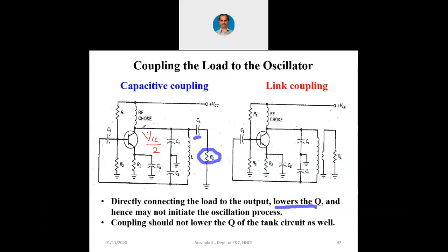Or if the resonant frequency is larger, then also the Q factor is larger, but the resonant frequency is the required frequency for the given application. So the only way to increase the Q factor is to have a reduced bandwidth. In order to have a reduced bandwidth, it is always advisable to have a high level tuning circuit. The tuning circuit's efficiency must be much better.